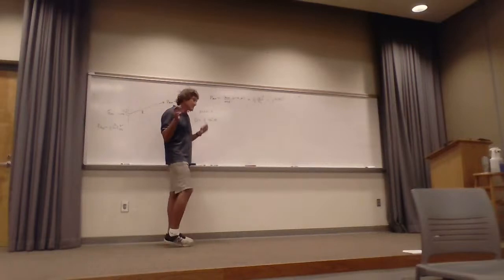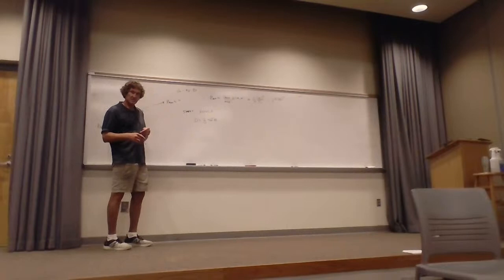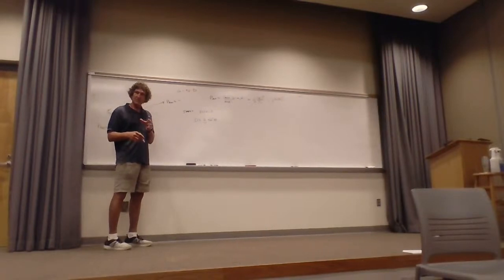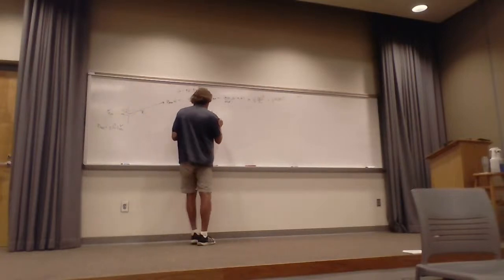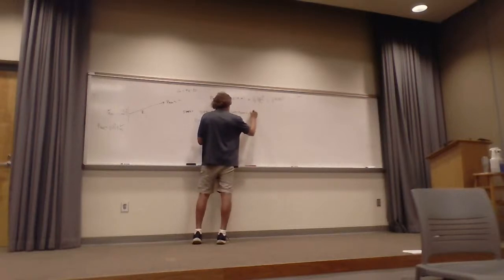I'm just trying to tell you that the directivity of a short dipole is this. And do you remember calculating 1.5 as the maximum? All right, maybe I better put it down as 1.5 times the sine squared of theta. And by the way, this is for all short or small dipoles.